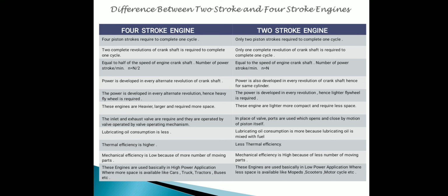Inlet and exhaust valves are required for the four stroke engine, but in the two stroke engine, instead of valves, ports are used to complete the process; with the engine running, the ports open and close.